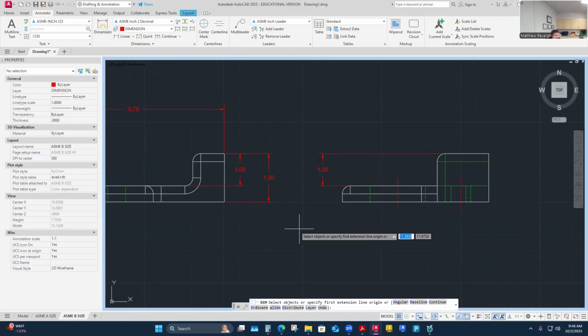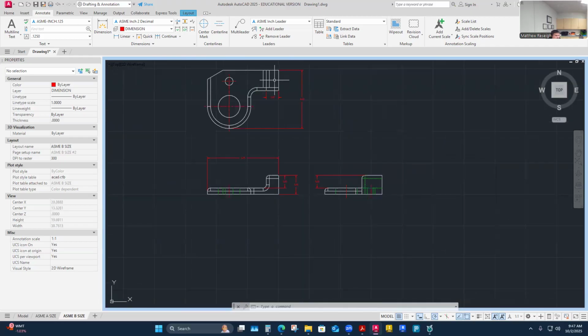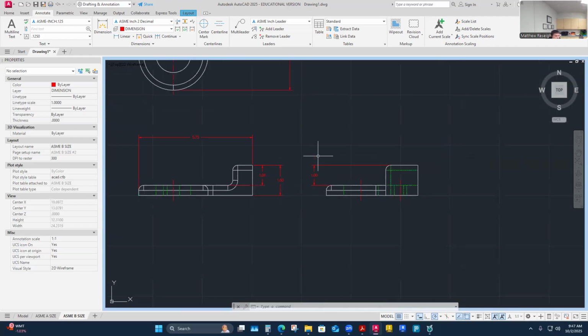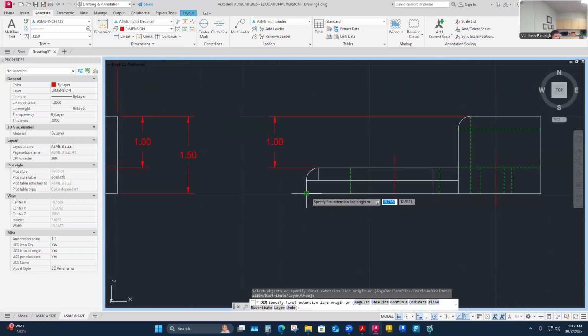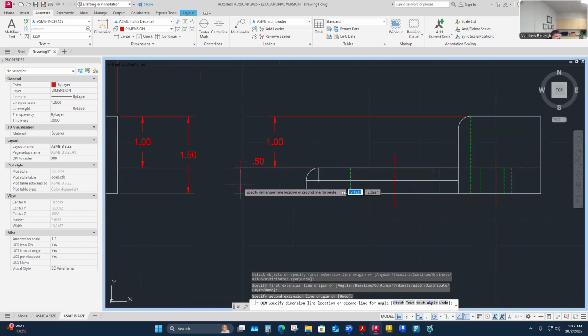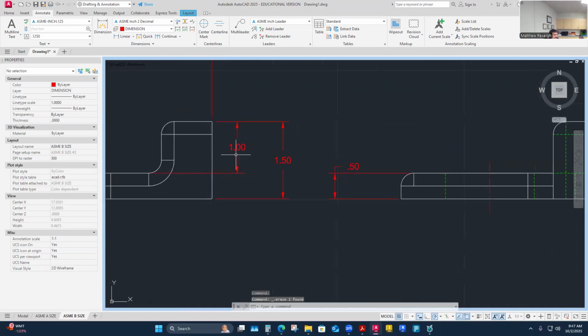If you think of this, what if I step back a little bit and think, even applying this dimension, I've now pulled it off of new datums, right? Somebody should have stopped me right away and said, well, then you just establish a new datum. I kind of established this top surface as a datum potentially, pulling maybe down to this feature, or I've established this as a datum. So now I'm needing to control how flat this is. But maybe the drafter that's paying a little bit more attention might say, I'm going to put this one in, and it's pulling from the same datum. I'm going to delete this one. I'm probably going to delete this one.